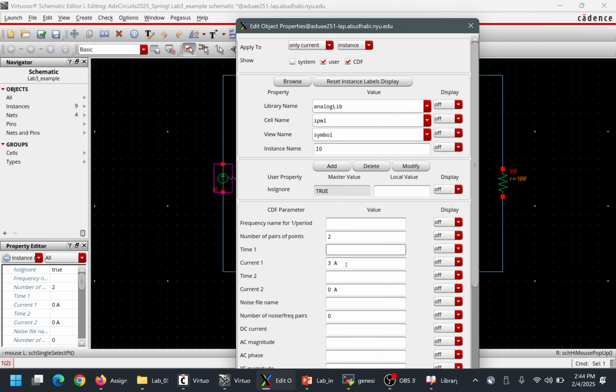All right, at time 1. What is that time 1? I said 1 second. We are saying that until 1 second, the current is 3 ampere, and at the very next moment it becomes 0. So that is 1.00, I don't know, choose whatever number, but then we have to be consistent with that number. Until 1 second, the current is 3 ampere, but at 1.00, the very next moment, the current becomes 0. That's what 3 u of minus t means.